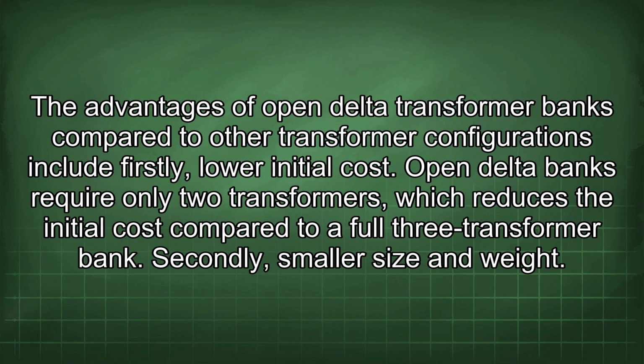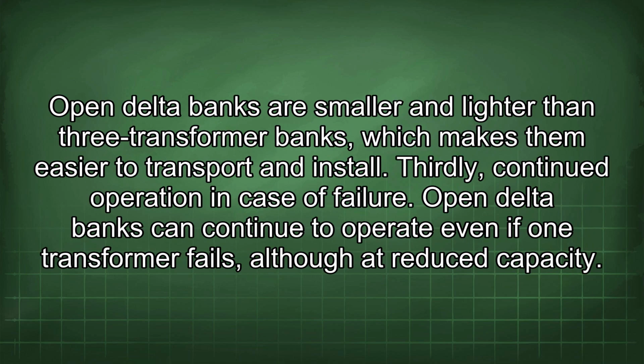The advantages of open delta transformer banks compared to other transformer configurations include, firstly, lower initial cost. Open delta banks require only 2 transformers, which reduces the initial cost compared to a full 3-transformer bank. Secondly, smaller size and weight. Open delta banks are smaller and lighter than 3-transformer banks, which makes them easier to transport and install.